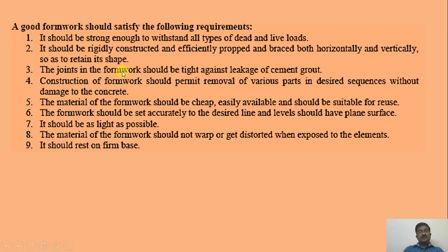The joints in the formwork should be tight against leakage of cement grout. Construction of formwork should permit removal of various parts in desired sequence without damage to concrete. The material of formwork should be cheap, easily available, and suitable for reuse.